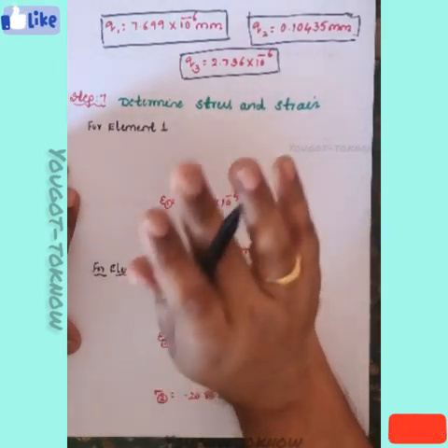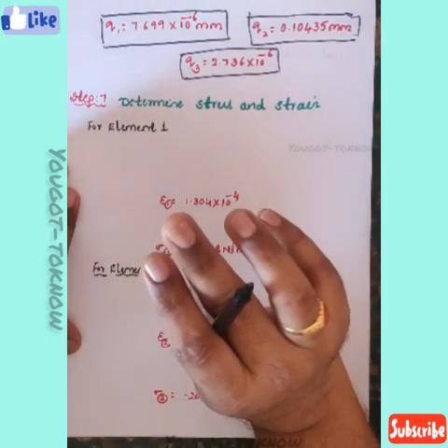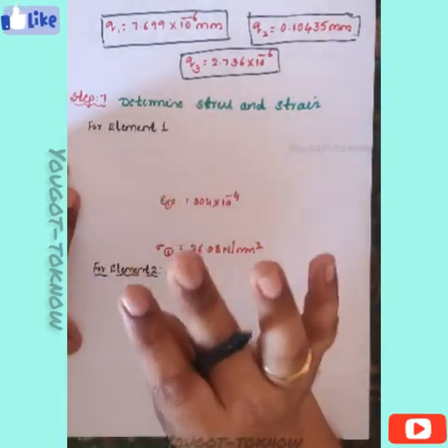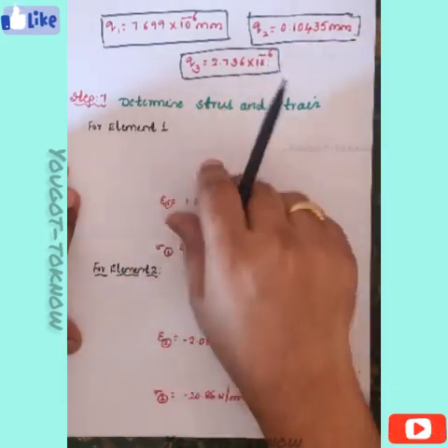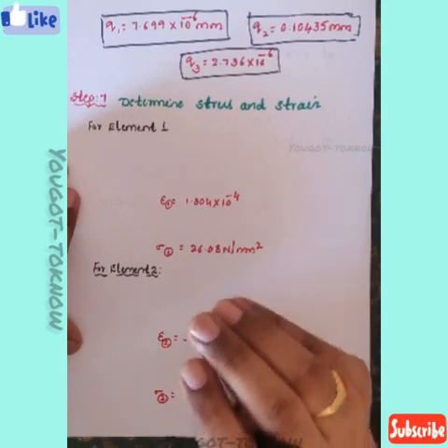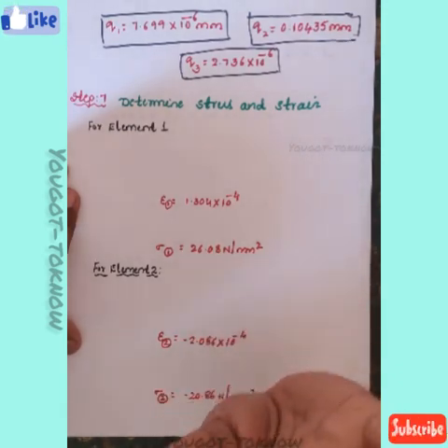This is what we do in the elimination method. Directly we will assume Q1 and Q3 as 0 in the elimination method. Why? Because we are expecting a very small displacement, so we directly assume it as 0. But here in your penalty method, we are showing that we are going to expect very small displacements, because it will offer a large stiffness at that particular point.